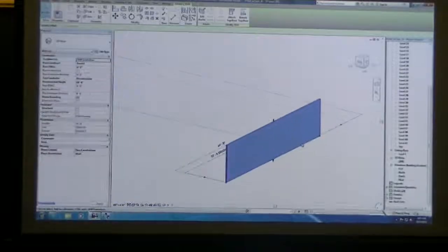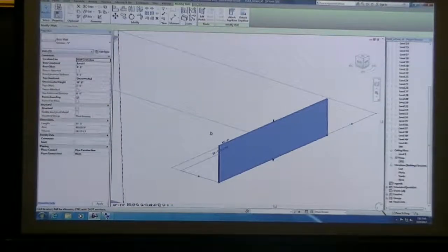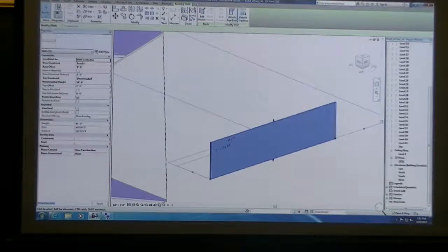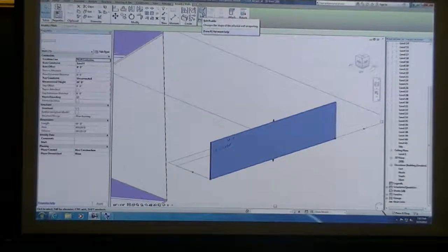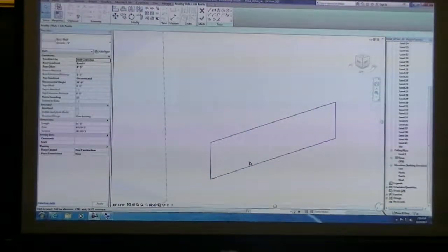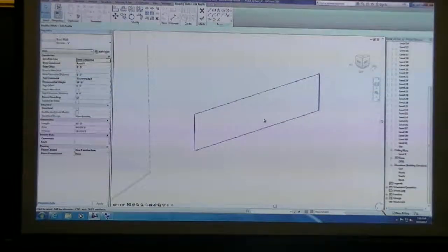if I click on this wall, that's your typical extrusion. At any moment, while you're in a 3D mode, or if you look at this wall in elevation, so if you look at either east or whatever, I guess we need probably a west elevation to look at that wall. Whenever you click on the wall, you also have these other options. You've got attach, top and base, detach, and then you also have edit profile. You click on edit profile, it gives you a purple sketch. You go into the sketch mode, just like with the floors and the ceilings and also roofs that we briefly went over the floors in last class.